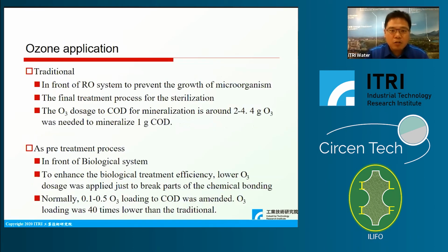In ozone applications, traditionally it was set up in front of our system to prevent the growth of microorganisms. It was frequently used as the final treatment process, not only for sterilization, but sometimes to prevent the accidental release of high concentrations of COD.